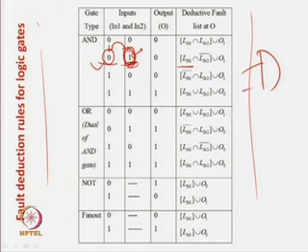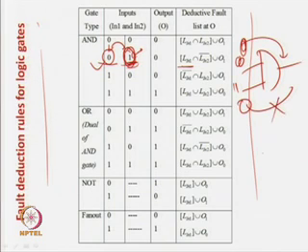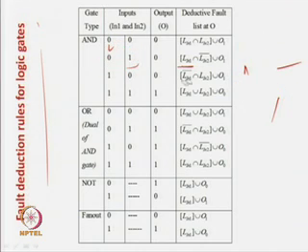Basically, this is the idea that this is 0 and this is 1. So, the fault list here will be propagated, and as this is a 0 and this is a 1, the fault list here will not be propagated. So, automatically it says that if there is something common between these two, then that will not be propagated, because whatever is here is not allowed to be propagated. So, how do we write this? We write it in a very simple way. We say L2 intersection L1 bar, that whatever is here will be propagated, whatever is here will not be propagated, and obviously the output is 0. So, a stuck-at-1 fault will also be detectable. This is the propagation list, and this is the fault at the output of the gate which is detectable because the output is 0 for this input.